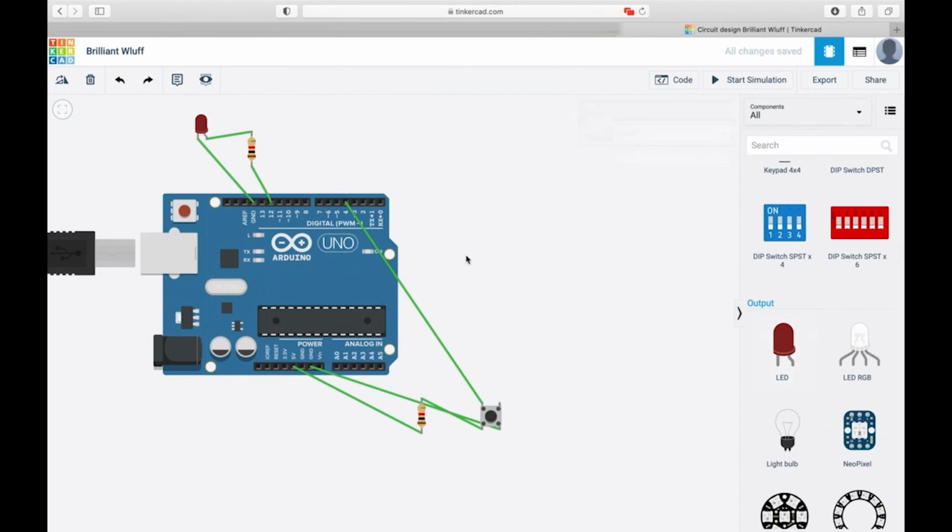Now my question is, you have to control this LED with this push button. You will take a condition: if this button is high, this LED should glow. If this button is low, this LED should be off. The state of the push button will control the LED. If it is in high state, that means if it is 1, this LED should be on. When you press it, that means it is in low state, that time the LED should be off.